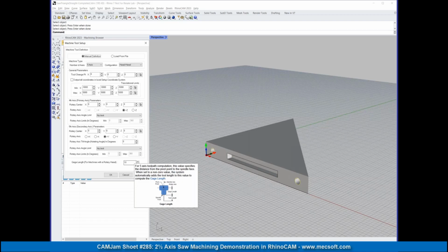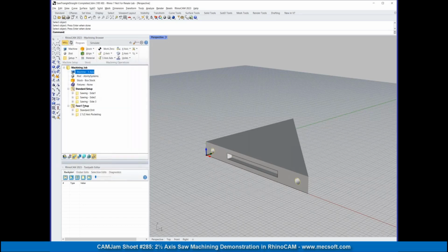That would be the gauge length, and that's what you input here. Gotcha. Okay, so we just touch it off with it pointed straight down, and then we would rotate it if necessary. Yeah, and you can rotate it any which way, and then we'll take care of the inverse kinematics for you, as long as we know how much to back off. Perfect. Yeah, once you do it once, then it's set with the machine, so you don't need to keep doing it as long as you do the zeroing the same way. Perfect. Okay. Thank you.